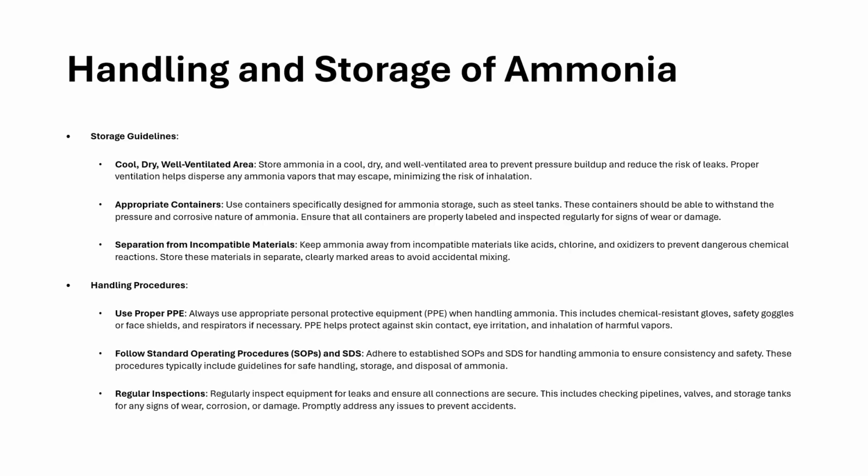Storage of ammonia. Storage guidelines. Cool, dry, well-ventilated area. Store ammonia in a cool, dry, and well-ventilated area to prevent pressure buildup and reduce the risk of leaks. Proper ventilation helps disperse any ammonia vapors that may escape, minimizing the risk of inhalation.